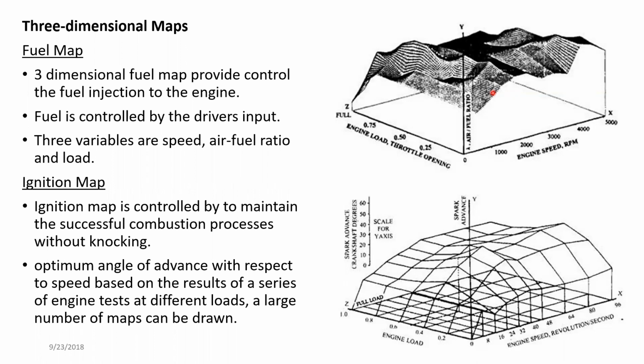If knock is generated while the fuel is being delivered, the engine load and engine speed identify where the ignition spark should be. Ignition spark is given, the fuel is combusted and the exhaust comes out. From the exhaust, the engine identifies that the fuel ratio is not up to the task, so the fuel ratio has to be changed a little bit. That is sent to the engine control unit, which informs the fuel control system, and the fuel control system trims down the fuel.